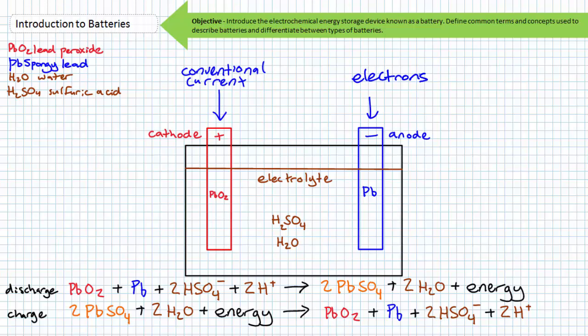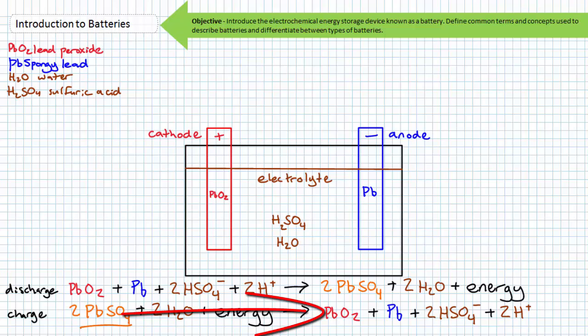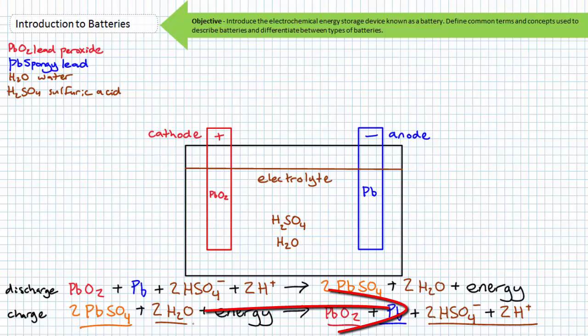The functional definition of the cathode and anode have changed during the charge process, but to avoid confusion, let's keep them the same. Again, neglecting stoichiometric checks and balances that so entertain the chemists of the world, what essentially occurs is that the sulfate is forced out of the spongy lead anode at the same time the sulfate is forced out of the lead peroxide cathode. The anode and cathode, via the charging process, become chemically dissimilar, and the chemical imbalance is restored. Additionally, the electrolyte becomes more acidic in nature and less water-like. The chemical reaction is essentially the reverse of discharge.